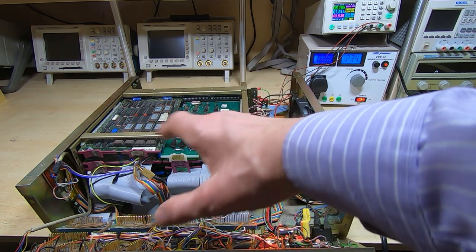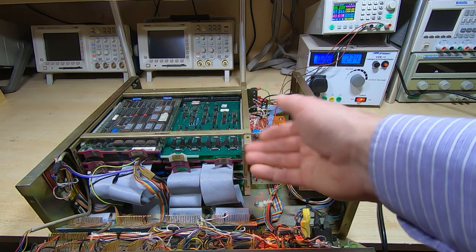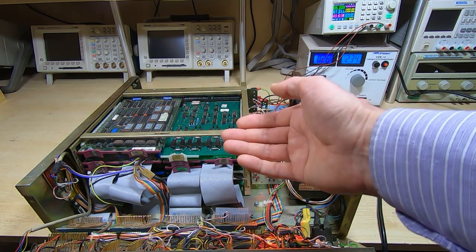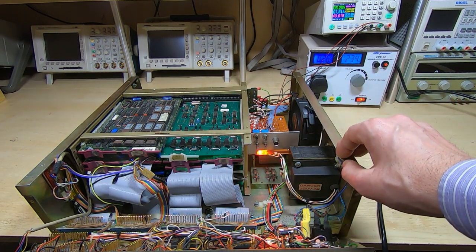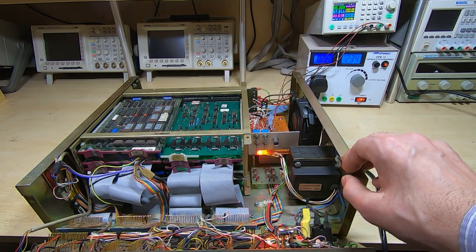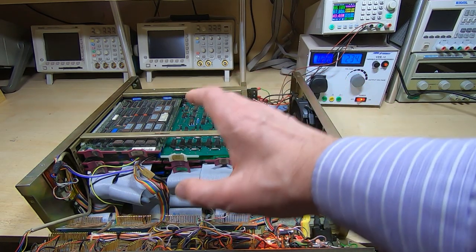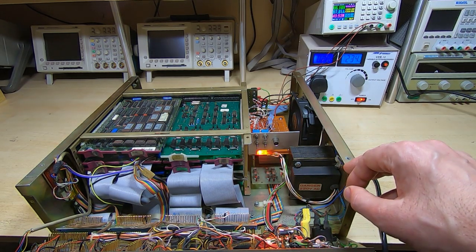It is possible it's some of the glue logic that's causing this, but it seems unlikely because if it was that, we tend to get issues in all addresses. It's only at specific address blocks that we seem to have an issue. I haven't been through them all yet, but we have at least one fault, so we need to resolve that before we go any further.